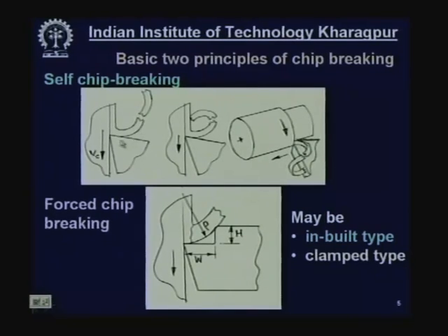At the rubbing surface, the velocity is high, and at the exposed surface, the velocity is low. Besides that, these two surfaces of the chip are subjected to different cooling rates, so the cooling will be effective at the outer surface and the rate will be different. So, this will become further curled and work hardened.